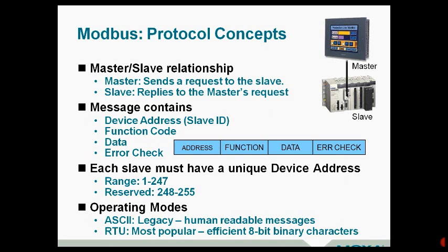and this is kind of the basics within Modbus. If you look at other industrial protocols, they share a lot of the basic core things that happen here. Another important concept with Modbus is that even if you have a point-to-point connection with RS-232, each slave device on your network has to have a unique device address, sometimes called a slave ID. If you're setting up a network, or some of you that have done this before know about this, you have to identify each device with this slave ID.